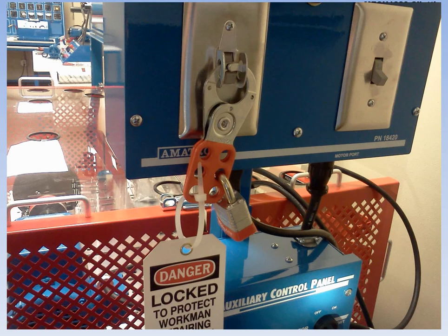So part of the lockout tag out procedure is each person has their own lock that is working on that machine. Because you don't want one lock for two guys, and one guy takes his lock off and goes to lunch. Well, the other guy is just sitting there working, and someone can come and energize the system and hurt you. So it's imperative that we can't power up the system until everybody's lock is off of it. And it's your key, and you're the only one that can take that lock off.